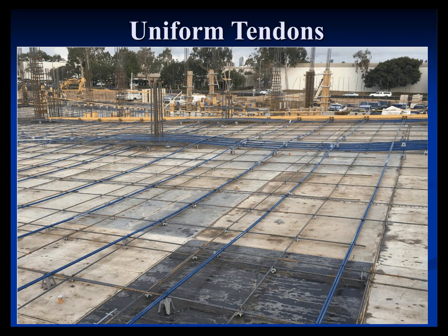As I mentioned before, we're talking about unbonded strands, meaning the strands are sheathed and greased, so there is no bond, no strain compatibility, between the concrete and the post-tensioning. They're completely slipped. The only interaction you get is from the anchors, when they're stressed, pressing into the concrete, and that pre-compression force emanating throughout the slab, and that's your P over A aspect of post-tensioning.